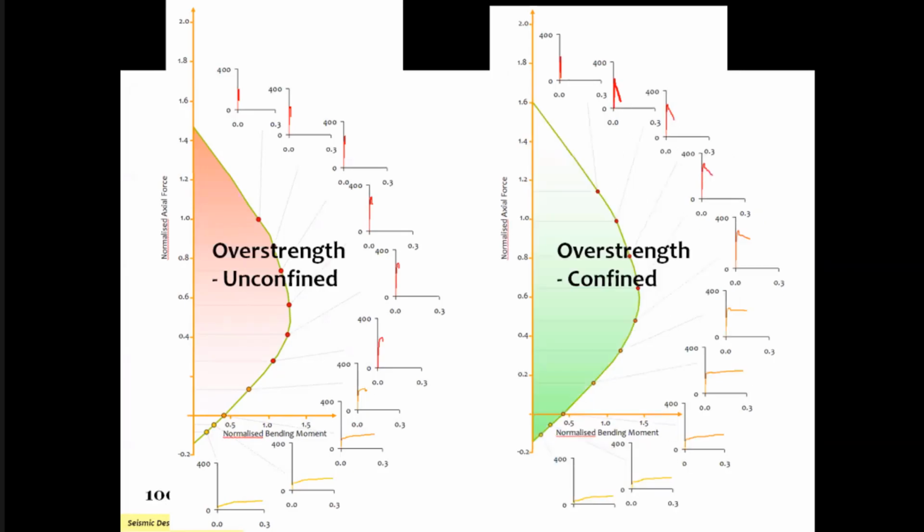Elsewhere, I will not comment, but if you are doing confinement, you will see that there will be a little rise in the behavior of these concretes in higher compression region, but the ductility is not much of a gain. The main ductility lies only in the lower axial load ratio, and that is where much of the ductile behavior is. So confining is essential for us, and choosing the correct cross section, correct grade of steel, and correct grade of concrete.